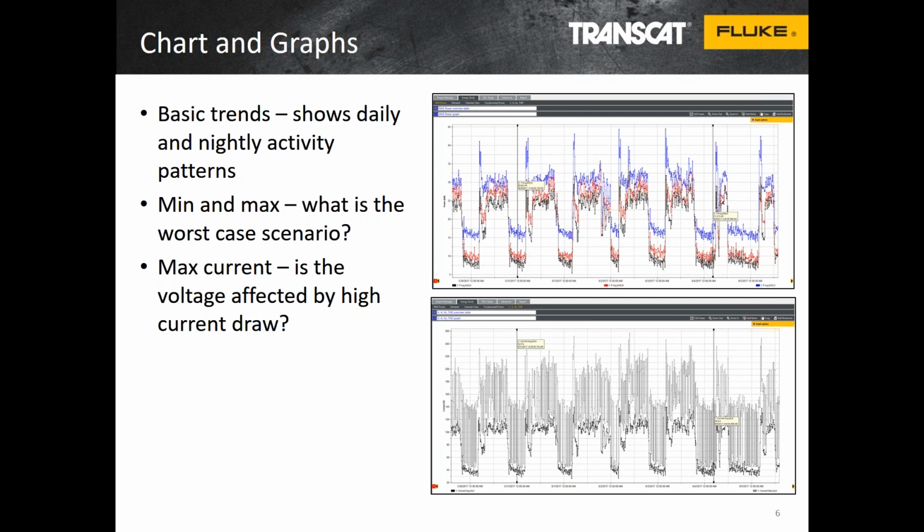The reason why we're interested in that is that we're looking really for exceptions. Why has something happened that we don't expect? Because that's an opportunity for discovering a power quality problem or discovering an energy savings issue as well. So you need to compare the values to correlate. It's normally if something happened, something else happens. So you have to look from multiple viewpoints to be able to see what happened.